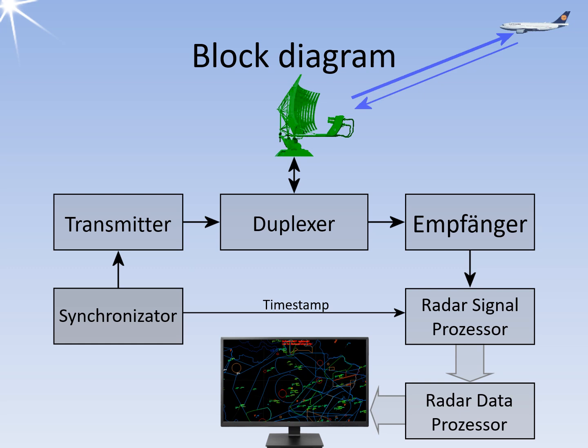In the radar signal processor, the echo signals are still processed as a signal, either analog or digital. Delays of 1 to 2 or 3 pulse periods are expected here, especially if a Doppler frequency is to be measured. However, the delay times are relatively constant, so one can still speak of processing in real time.